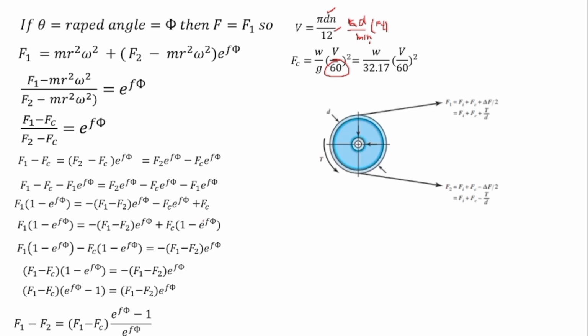Now after that, let's consider this belt that is wrapped around this pulley. Now what kind of forces will be exerted on this belt? When you are manufacturing this belt, you will have to give some initial tension to this belt. And similarly, since this is rotating in this direction or in this direction, so there will be centrifugal force as well, and those forces will give further tension to the belt. So we have added FC over here, similarly Fi over here and over here as well.